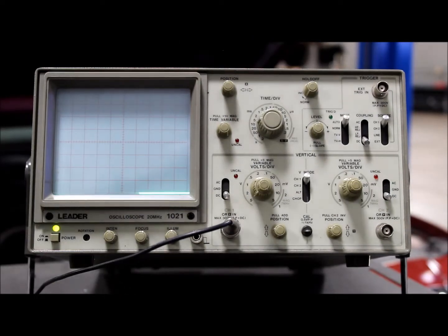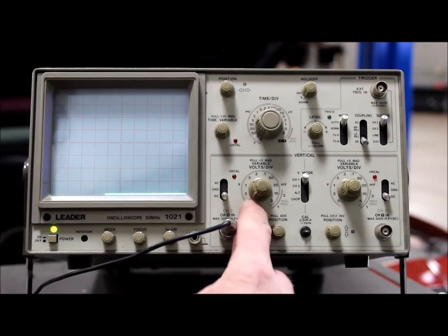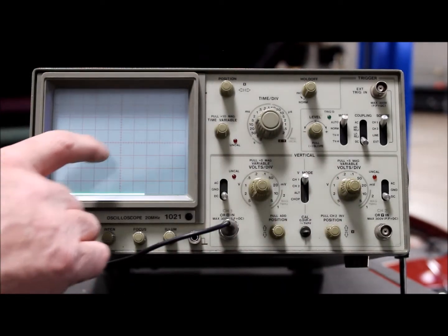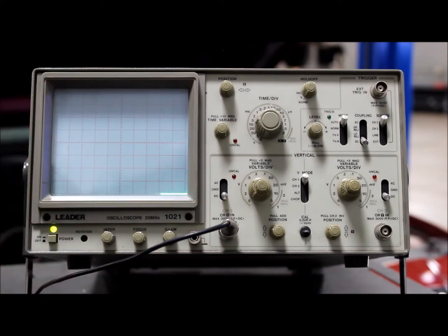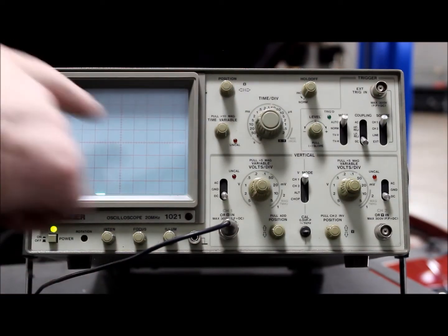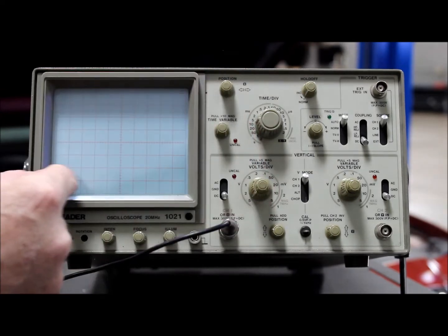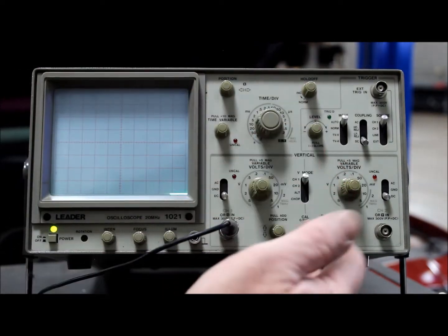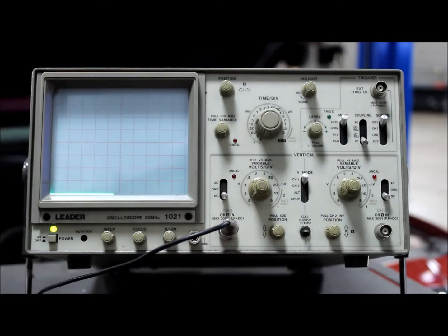I have this oscilloscope set up and connected to the number 1 fuel injector. It's connected to the negative wire, the wire that's grounded by the PCM. So right now, I have the scale set to 5 volts per division, so 5, 10, 15, and the time is about 5 milliseconds for each block. Hooked to DC, we're looking at channel 1, which is what I'm plugged into.